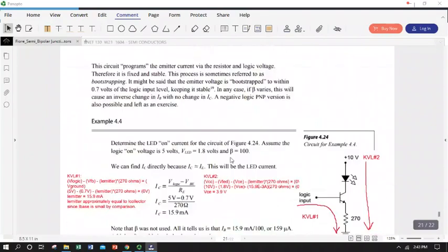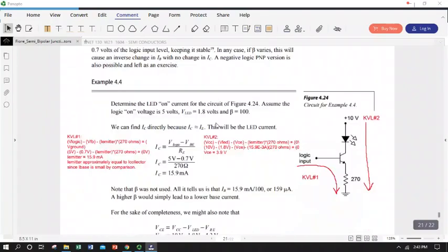So we just apply Kirchhoff's voltage law and what we know about the base emitter junction, and we let the circuit tell us where it's operating, basically. But we can always define those endpoints of the DC load line by assuming either zero collector current or zero collector emitter voltage. So we can at least define the endpoints.